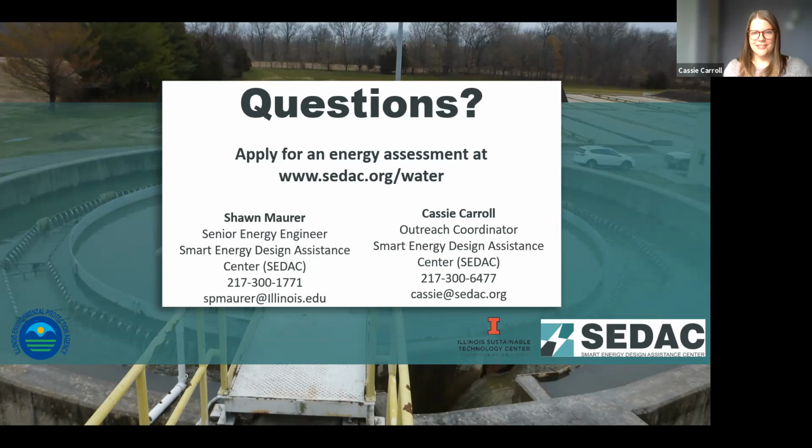Awesome. Since we do have some wastewater folks on the call too, can you address what we've found as some good tips for wastewater facilities as well? Sure. For wastewater, aeration tends to be the bigger energy consumer there. So, looking at optimizing aeration processes, either adding DO or ORP meters to your aeration process, high efficiency aerators, looking at your blower controls, and potentially blower upgrades are the bigger projects for wastewater plants.